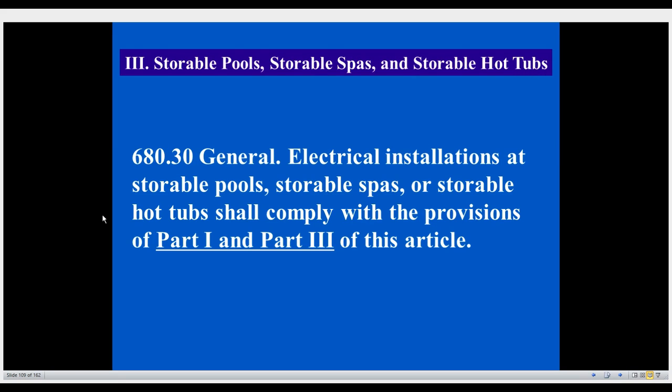All right, so 680.30, what is it telling us in the general requirement? Things that we have to understand up front. Electrical installations at storable pools, storable spas, or storable hot tubs shall comply with the provisions of Part 1 and Part 3. So we're in Part 3, so we meet these requirements. Now, we're also going to have to meet the general requirements of Part 1. And that is in Part 1 of this video series. Go back and watch that. That is all the general rules that we have to follow.